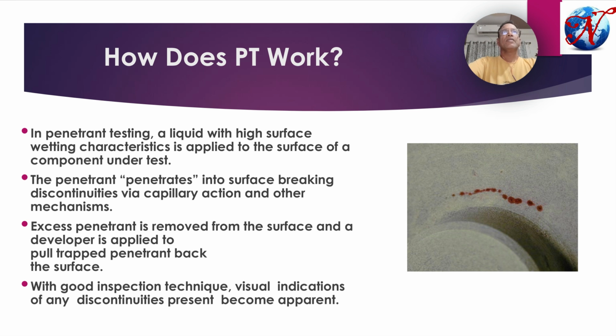In liquid penetrant testing, we clean our inspection surface by the application of some solvent or cleaner, and then we apply the penetrant. After a certain time period the penetrant will be removed. The penetrant will be entrapped into the cavities by the process of capillary action, and when the entrapment is completed, depending upon the opening of the defect, size of the defect, surface wettability condition, temperature of the job part and type of defect also, which is known as penetration dwell time, excess penetrant is removed from the surface, and then we apply the developer solution.